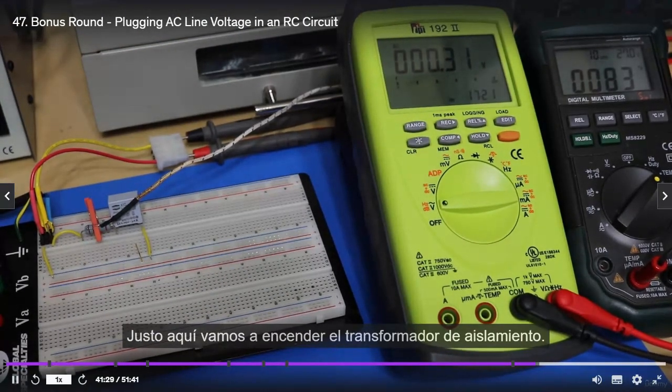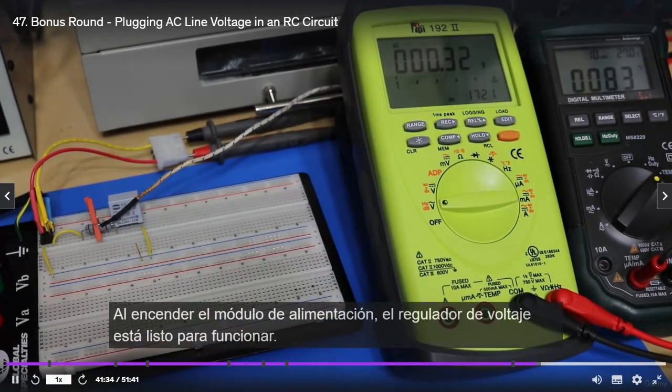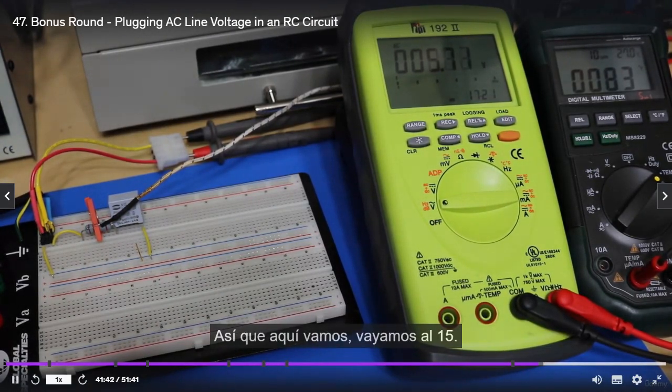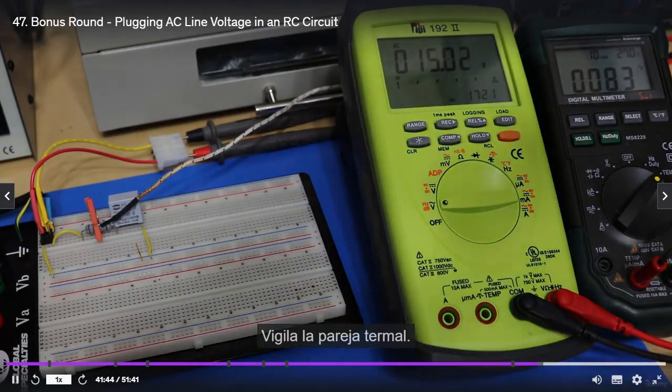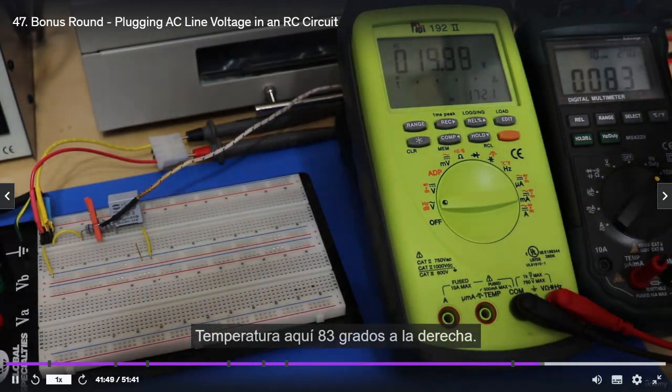Here we go. Turning on the power to the isolation transformer, good to go. Turning on the power module here, or voltage regulator, good to go. And now I'm going to start turning the Variac. Right now we got nothing, so here we go. Let's go to 15. Keep your eye on the thermocouple temperature right here, 83 degrees, right?